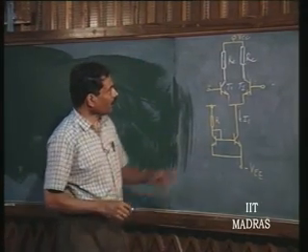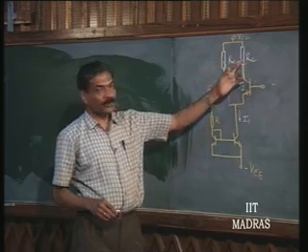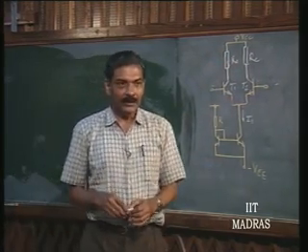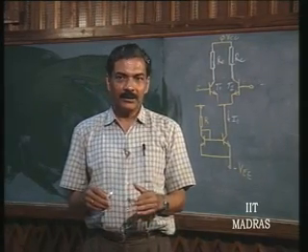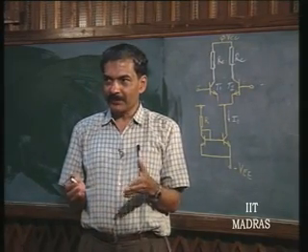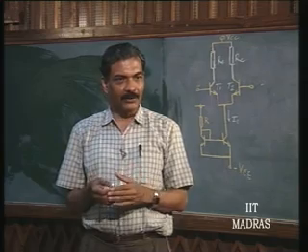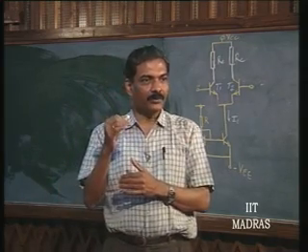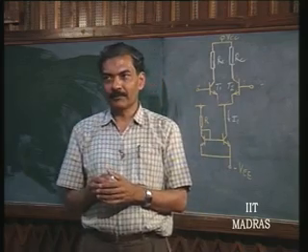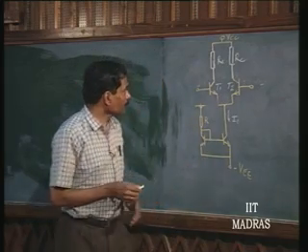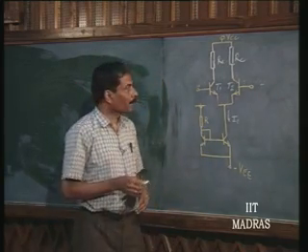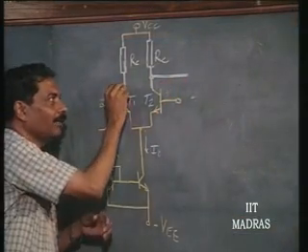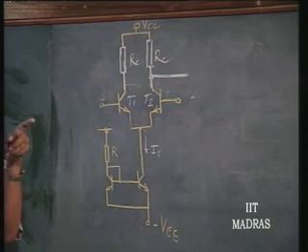We had noticed how replacing the two resistors by means of a current mirror has resulted in a gain which is the same as that of the earlier differential mode gain, but with reference to ground, you are now taking the output from one collector alone. Now, please remember that normally you are connecting the next stage, which may be another differential stage.